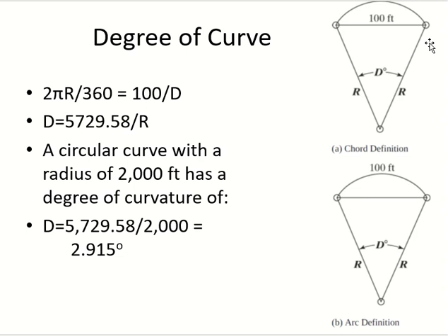So what is the relationship between degree of the curvature and radius? You know what is radius, right? Now what is this 2 pi r? Circumference, right? And what is this 360? Degree of the whole circle. So the circumference of the whole circle is 2 pi r, and the angle of the whole circle is 360. Some of you are trying to remember it. There was a time when they taught you this and you forgot. Now just believe it.